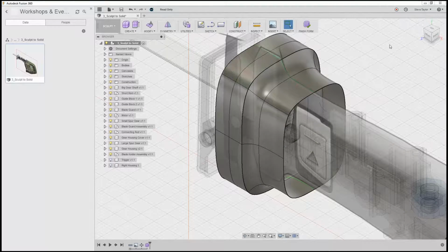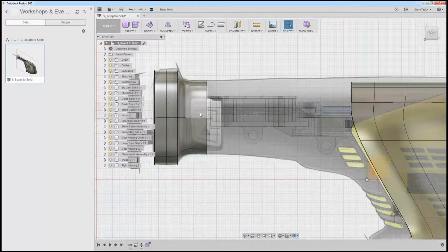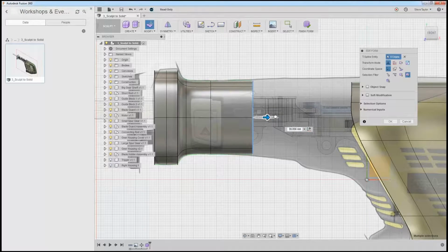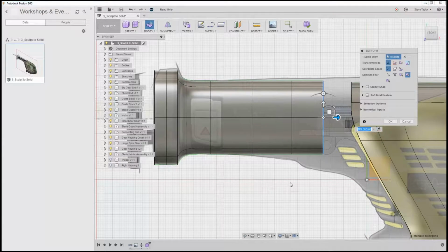So what I want to do now, I want to add 3 more faces onto here and bring it in a little bit. So again, just like before, I want to start bringing it down into this. So I'm going to modify, I'm going to double click this edge, then using my Alt key, just to add 1, 2, just 3 more, there.